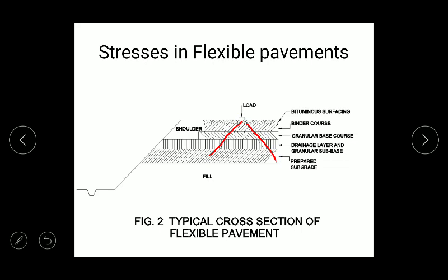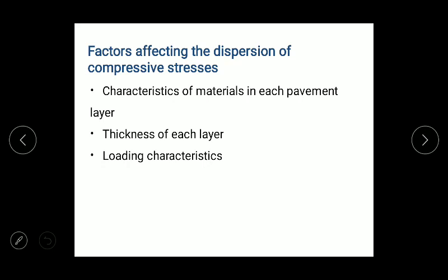Fill or embankment, and second is the prepared subgrade, and after that is the granular subbase, which also acts as a drainage layer, and after that the granular base course, that is wet mix macadam, and after that binder course, and after that bituminous surfacing. Okay. So next, coming to factors affecting the dispersion of compressive stresses.